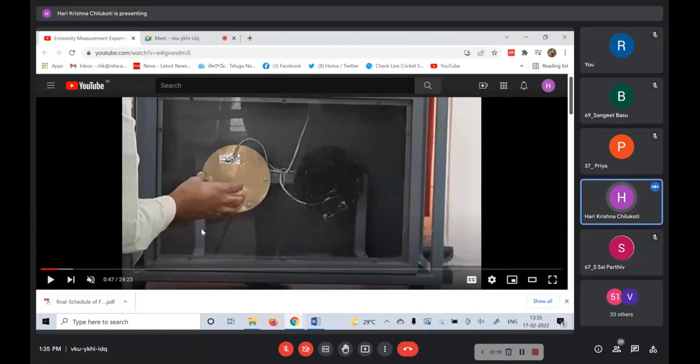This entire frame on which the two plates are mounted is positioned in an enclosure, generally speaking, so as to minimize the heat loss from convection, particularly by forced convection. Again, the contact between the frame and these plates is kept to a minimum so that the heat transfer by conduction is also minimal. Particularly, we will neglect that component in the analysis.